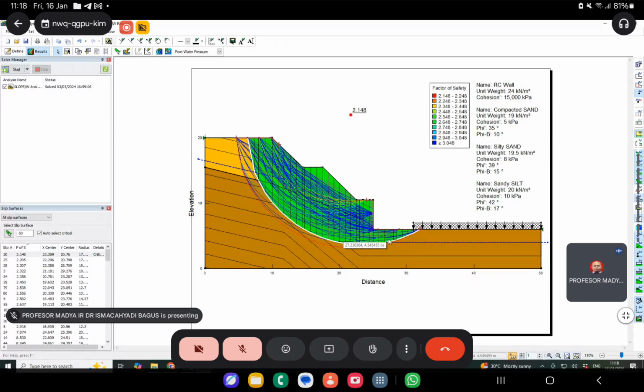moment rotation, sliding, bearing capacity is also to be checked. That one is designed by the consultant. So the consultant's design gives me the dimensions, they provided me with the dimensions, then I just check for the global stability, right? So it must follow the design criteria as set by JKR. To be safe, use JKR specification. Okay.